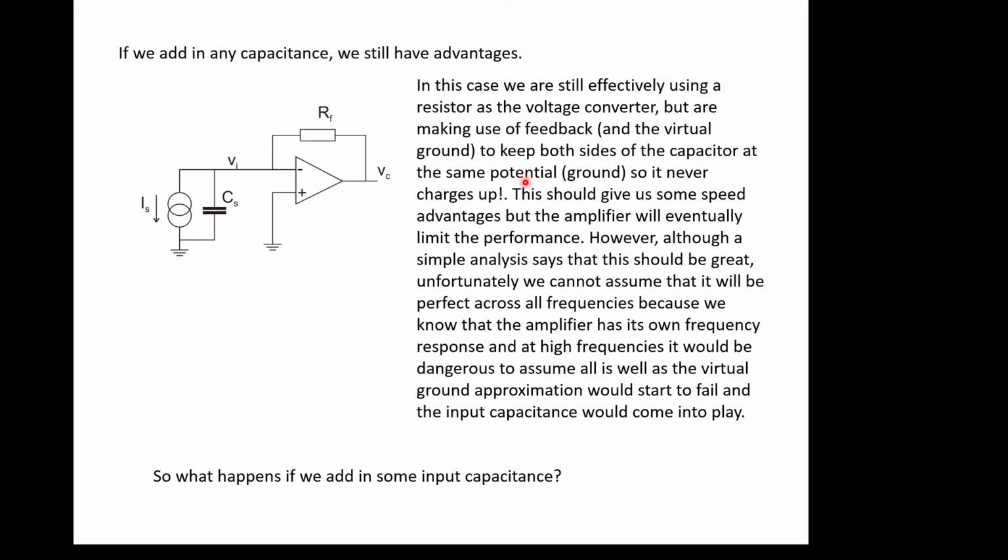So just to show what happens if you put in the capacitance, what happens is it should have no effect because, as discussed, we've got a virtual ground here. So the voltage across this capacitor is always 0. What do the words say? Yep, so that's what we've just discussed.